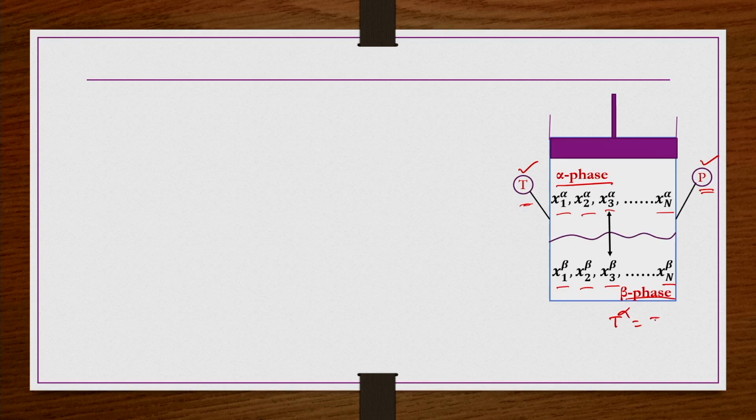separately. Okay. Now, there is a transfer of species, mass transfer also occurring from one phase to the other phase. So, what should be that composition that we have to find out, but how to represent that equilibrium because of the mass transfer? Because thermal equilibrium we know that T alpha equals T beta equals T, so only one T we are writing, right. Similarly, mechanical equilibrium we know that P alpha equals P beta, so only one P we are representing. Similarly, when there is a transfer of species, so then what is this?